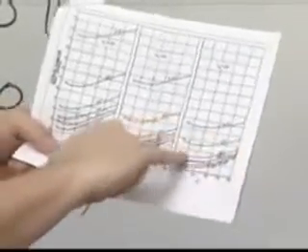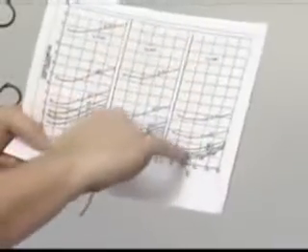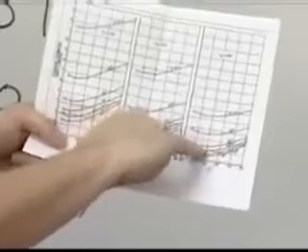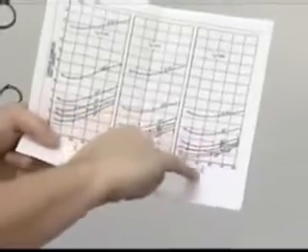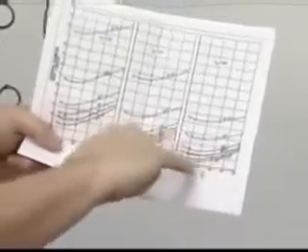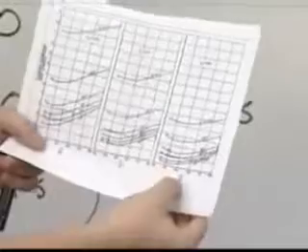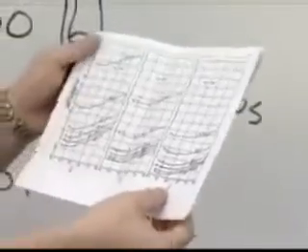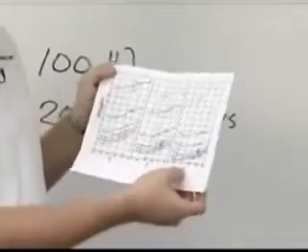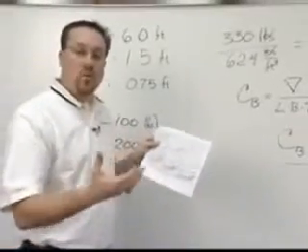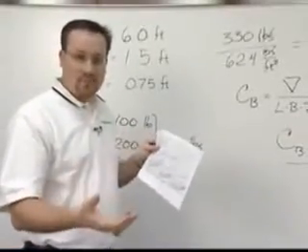Okay? So you want to look for a 30-degree curve on the block coefficient of 0.8 and find out where it's the smallest. Okay, I can read this line and find out where the smallest is, and it comes out at a value along this axis of about 45. Okay, so we're going to use that number, 45, in this equation, 1 over A prime t. All right. Next, I'm going to show you what you do with that term and how you can convert that term into a dimensional rudder size for your boat.